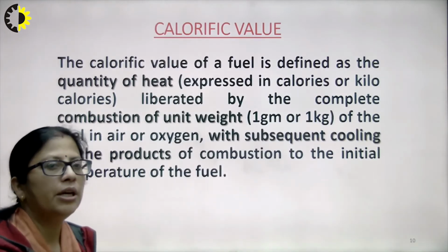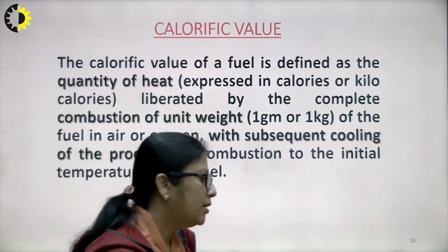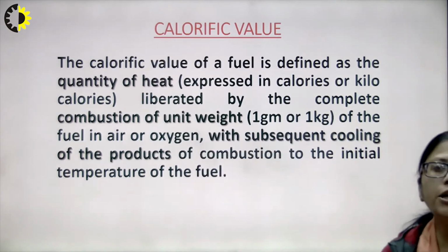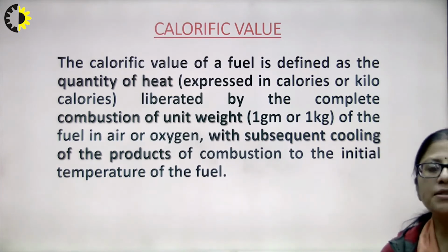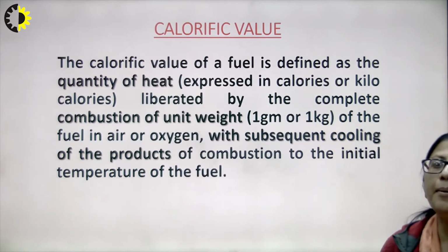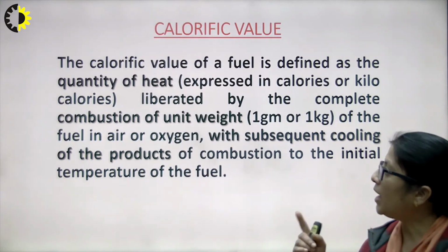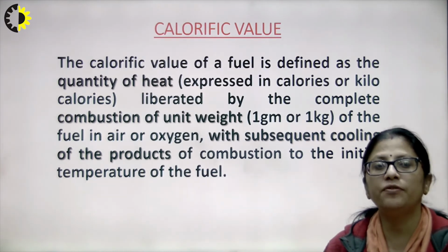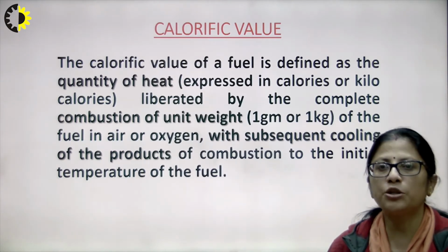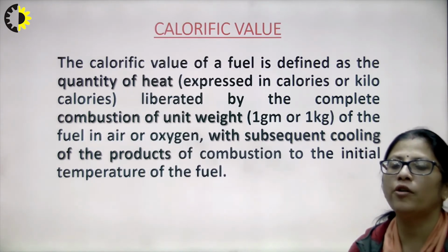Now, coming to the calorific value, what do we mean by calorific value? The calorific value of a fuel is defined as the quantity of heat, expressed in calories or kilocalories, liberated by the complete burning of unit weight, 1 gram or 1 kilogram, of the fuel in air or oxygen, with subsequent cooling of the products of combustion to the initial temperature of the fuel.